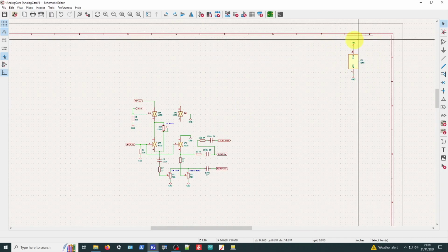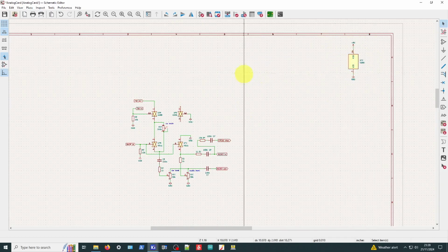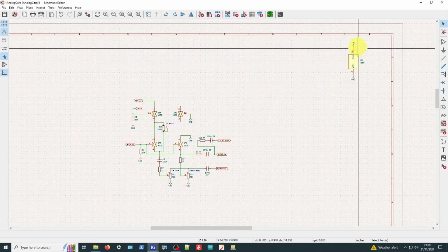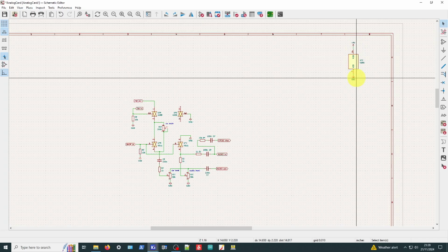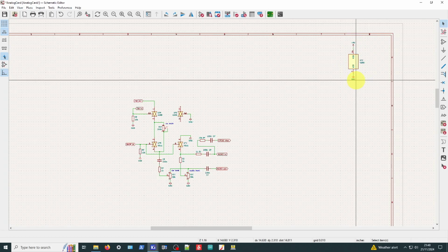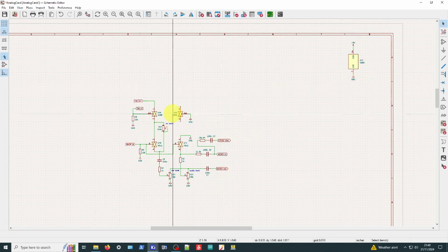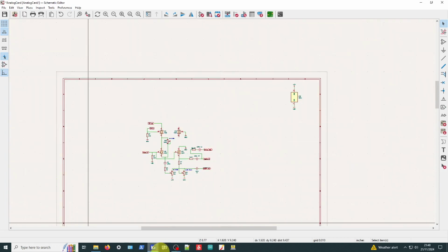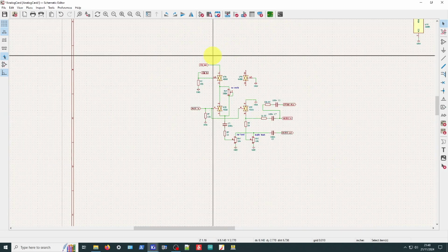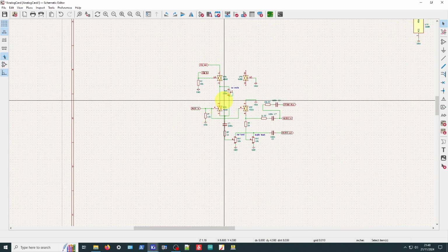But they do need to be connected for when you come to do your design rules. Everything has to be connected. It will check whether the power pins are connected or not. If they're not connected, it'll give you an error. So they do need to be connected. And any other chips or rails that you add will all connect up here. You can put them anywhere you want, you just drag them around. Let's just say the power is taken care of because of that symbol up there.